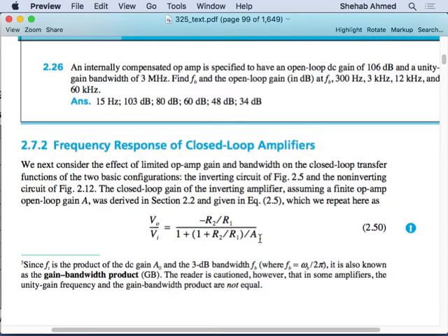Because now A is fixed in magnitude, but assumes the bandwidth is infinite. Now I will want to limit the bandwidth as well. So how do I do that? I plot A as a frequency-dependent function that looks like a low pass filter, by knowledge of ft.